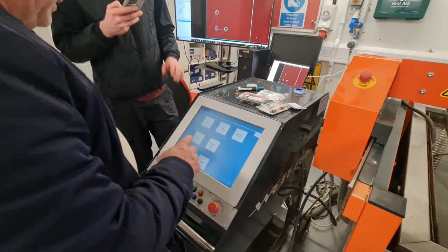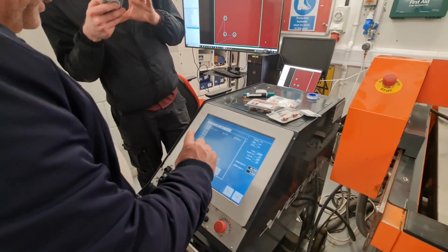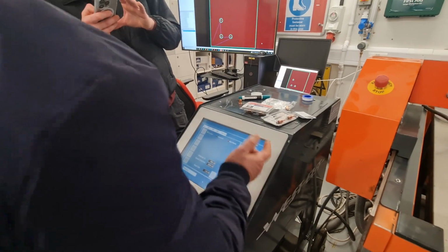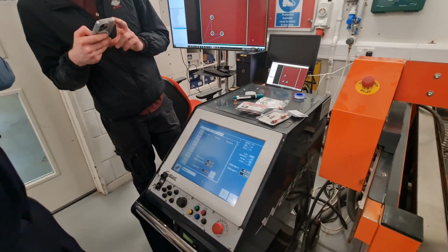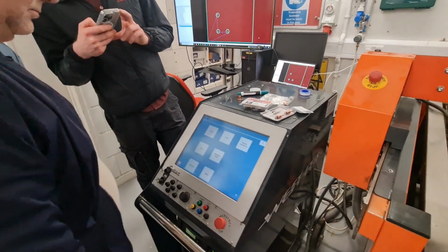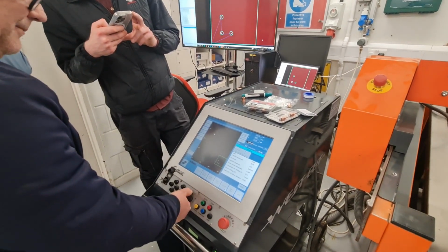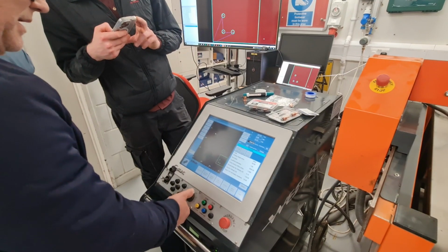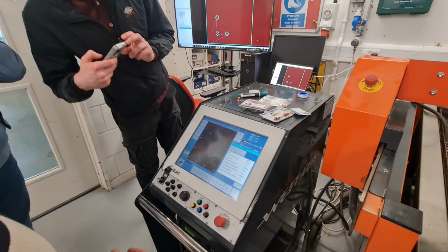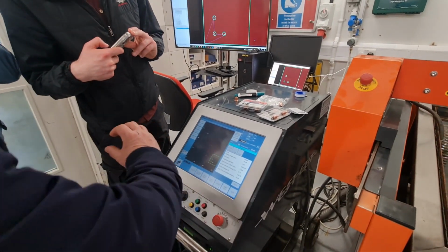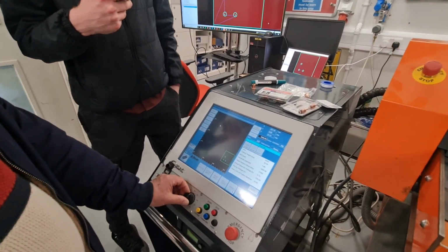Now there is another parameter that should match. Now it's the other way, okay? It's minus 86, not plus, because we are switching the torches. And the Y is always there. Okay, this is the override feed rate. This should be more or less always 100. But if you see the machine is not cutting well, you can go a bit slower or a bit faster. This one here. So it's like a percentage. Yeah.